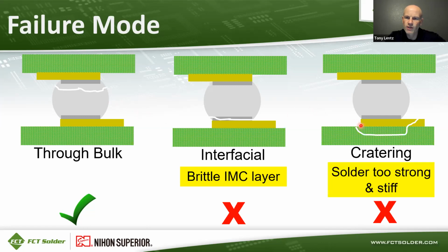And then pad cratering is where the board pad is actually removed from the board. It's ripped off of the board because the solder is too strong. It's too stiff. And so in that case, you're totally destroying the circuit board and it's not repairable.